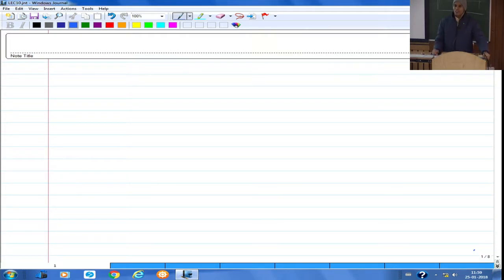The rod problem we did using the 2 noded, 2 element discretization and 1 element quadratic 3 noded element. Obviously, when we saw the assembled stiffness matrix of 2 noded 2 truss elements and the stiffness matrix of just 1 3 noded element, they are different, and in general they will always be different.